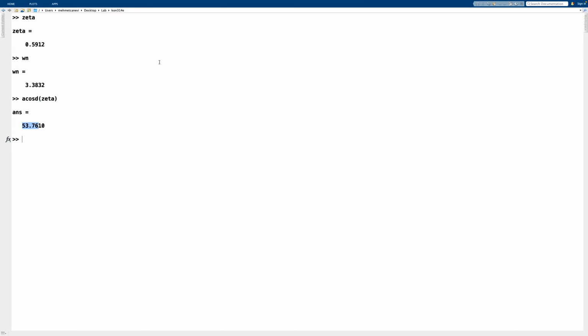The intersection of both the positive angled line and the negative angled line with the circle at the origin with omega n radius is going to be your design point, or your choice of complex conjugate poles. You can, of course, directly conclude what the real value is going to be, because zeta times omega n gives you the real part, so it's going to be -2 on the real axis.